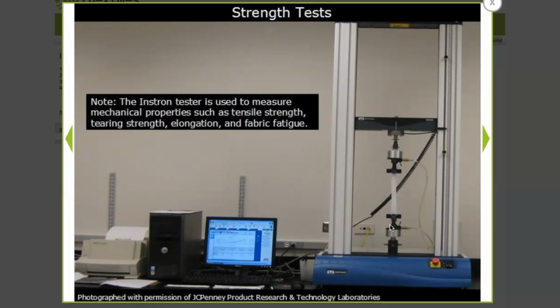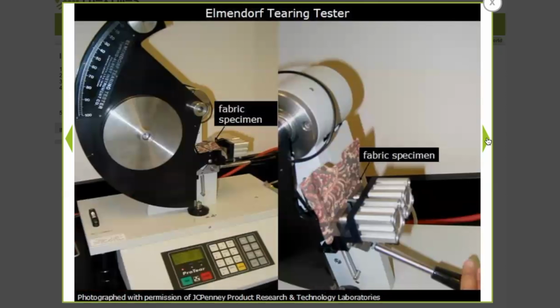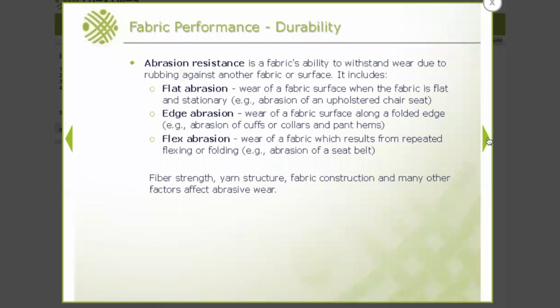So if a fabric takes a lot more power to break, that means it has better tensile strength. But if it breaks with just a little bit of force, then it means it has low tensile strength. So tensile strength is all about durability of the fabric, the strength of the fabric. We also test the bursting of a fabric with pressure. So you take a fabric, you put some air pressure, and you measure how much pressure it can withstand before it bursts. These are tearing testers and so on.